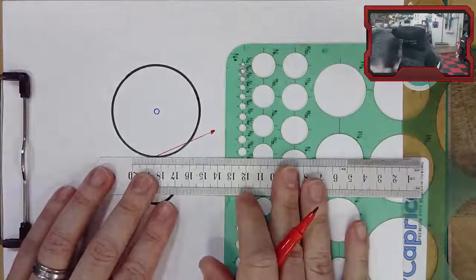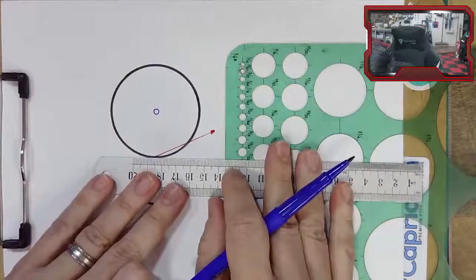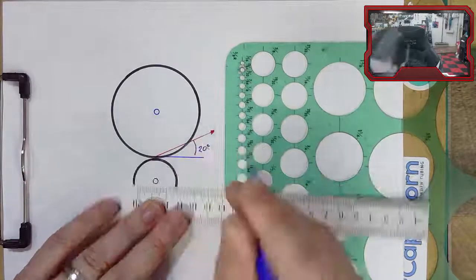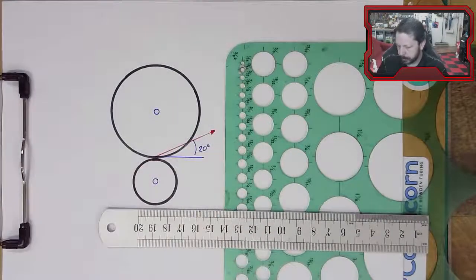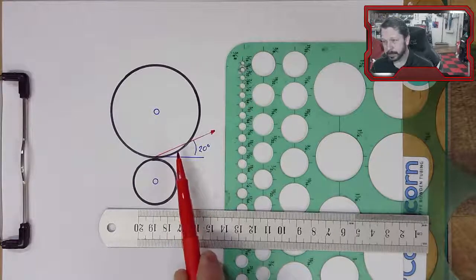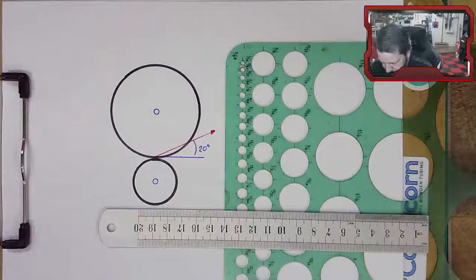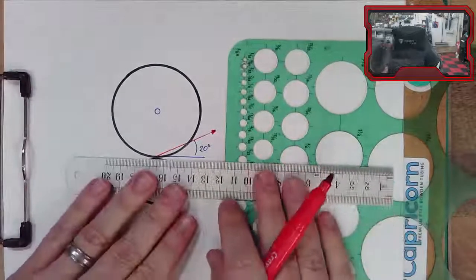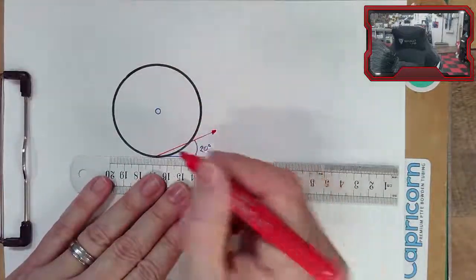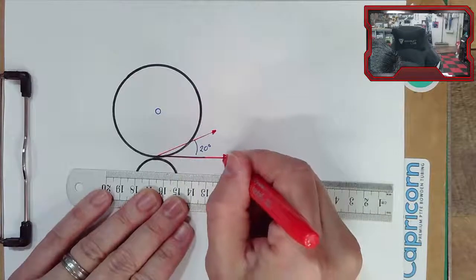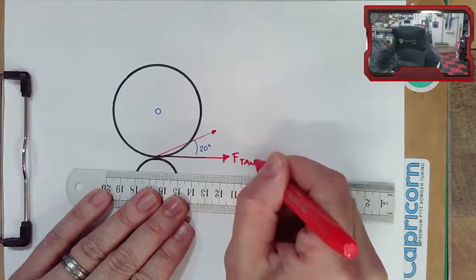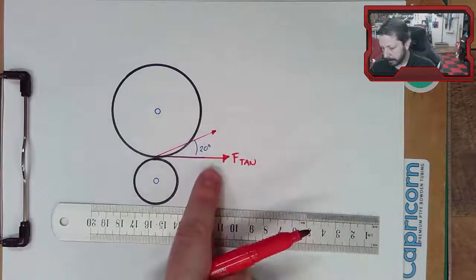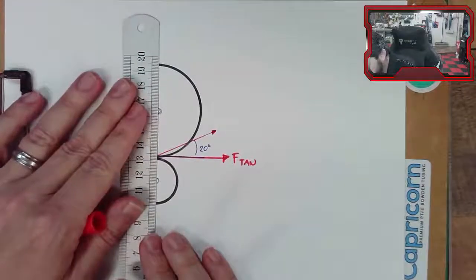So the 20 degrees would be, let's draw it in this color, something like this. So that's the 20 degrees. So this pressure angle means that if I take and find the components of this force, there is one component that is horizontal along this blue line. So I do have one component. I'm going to call that the tangential component. And then to create this angle, I would have a horizontal component, but I'd also have this, I'm going to call radial component.